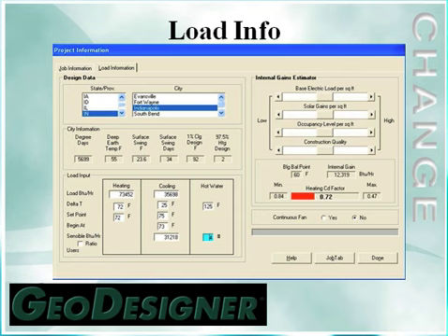Once the Manual J load calculation has been completed, we're going to input the heating BTU requirements and the cooling BTU requirements, and in the cooling section, we need to know not only the total load, but also what our sensible load is. We're going to put in our delta T that you used in the Manual J load calculation. The program needs to know what the temperature difference is from inside to outside that you used for your load calculation, as we spread those BTUs through the entire window of the bin data that will apply for the region selected.